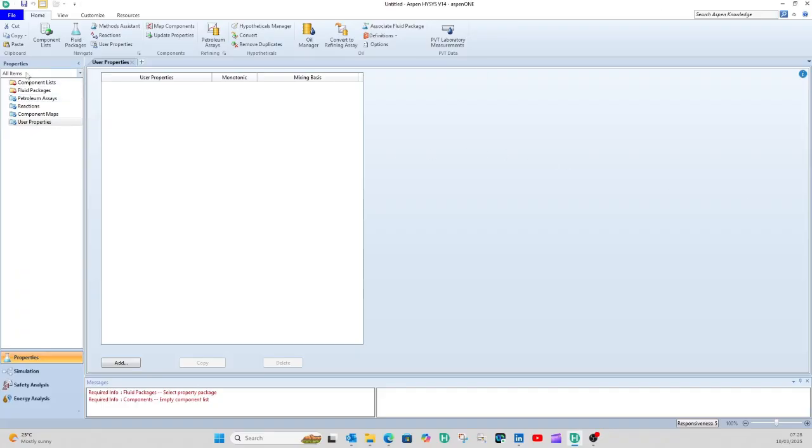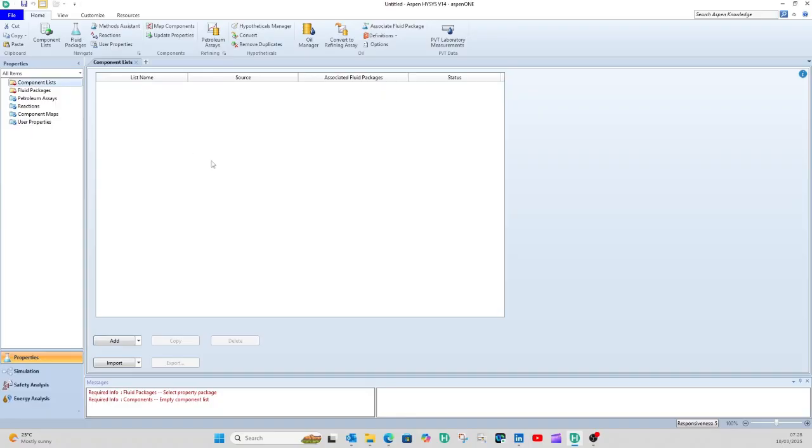So we'll be specifying the component list. When you click the component list, before we simulate, we have feed components. Our feed comprises a component list, different constituents, different compositions, different components. Maybe if it's a natural gas feed, we might have methane, ethane, propane, CO2, and H2O if there's some amount of water in the natural gas stream. So these are defined as our component list. You cannot just start simulating. No, you have to define these component lists.